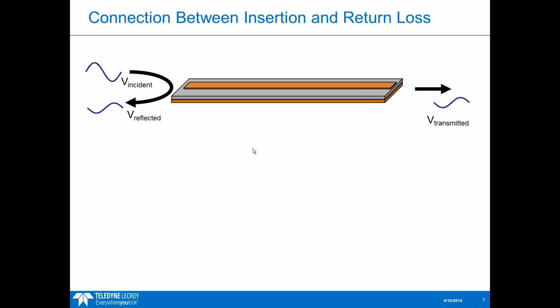Yeah, so this is kind of it. There are some different techniques that can be used in a frequency domain instrument. You use a directional coupler. A directional coupler will pick off the signal only in one direction. So we have some calibrated signal we send out, which is this incident signal. And typically there's a calibration process that's done, so this signal is really well defined, the incident signal. And then a directional coupler can be used to pick off only the signal coming on the return.